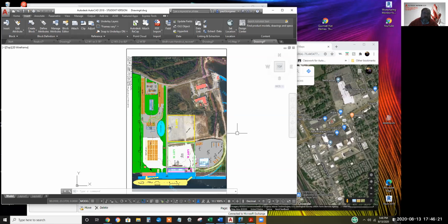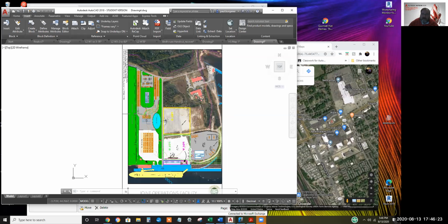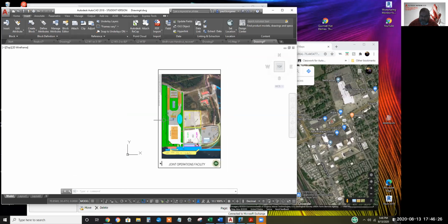Another use for images: I have a lot of gaskets and bicycle sprockets and lots of flat pieces that are scanned in, along with a tape measure in the scan. You can scale that scanned image of the bicycle sprocket so the tape measure is accurate and heads-up digitize the sprocket.